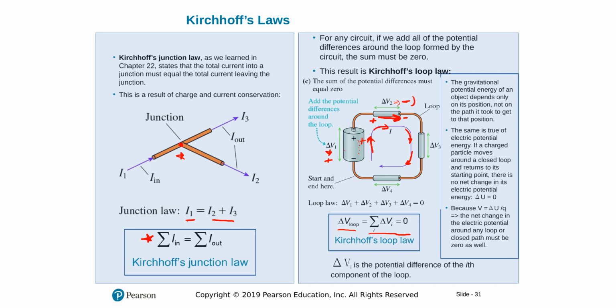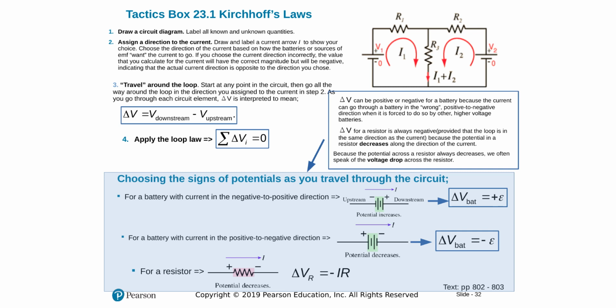So across a resistor, I'll be taking the potential difference as negative if I'm walking in the same direction as current. Same thing here, I'm walking along the direction of current, so it's plus to minus. This guy will also be minus, and so on. The same thing here, minus. That's the idea. And this page summarizes that.